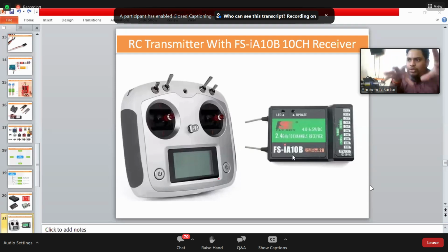So it is possible to build a drone with Arduino Nano and Arduino Uno, and even with RPi. But the problem is the stability of the drone, because we need to put in a barometer, accelerometer, magnetometer, and some kind of meter that helps put the drone at a certain level, so that the drone can get the information that yes, I am in this position.